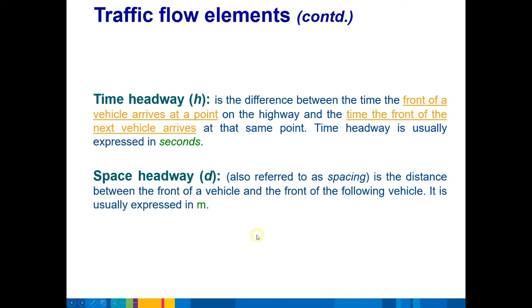Okay, another point to note is time headway. This is the difference between the time that the front of a vehicle arrives at a point, and the time that the front of the next vehicle arrives. Time headway and space headway are similar concepts to describing wave functions. If you remember in the discussion of waves, we have a crest and a crest, and the distance between the crest and the crest, we define as a wavelength.